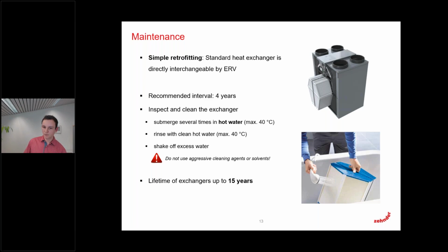And how to do this? You can just do it with hot water. Take a container, let hot water into it, but this hot water should not exceed 40 degrees Celsius. And then you can submerge it several times, rinse it, and shake off the excess water, and then you can put it back into the unit.